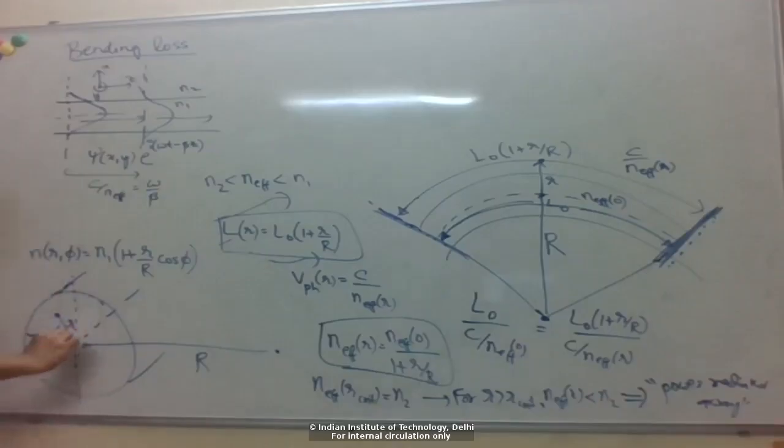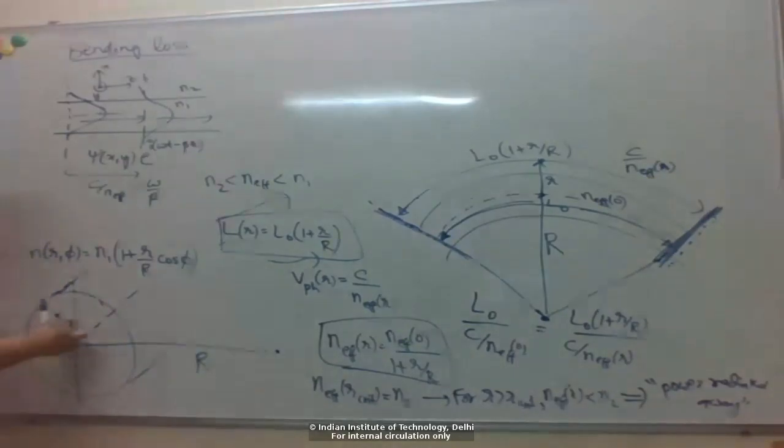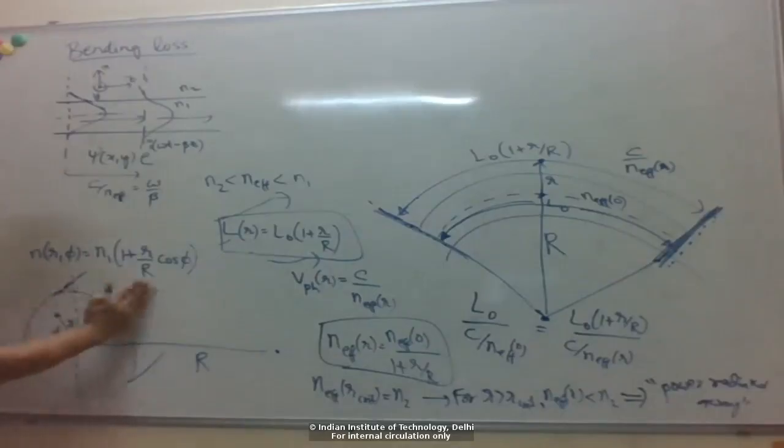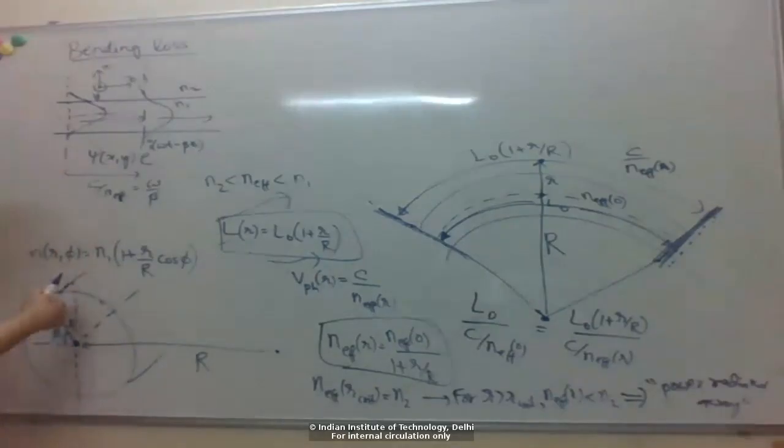And if you take, so imagine now phi equal to 90 degrees. That's a plane which is perpendicular to the radius of curvature here. Points along this are all traveling the same distance. On this plane, because it's bending into the board, all these points are traveling the same distance, unlike for this axis here, where all these points are traveling different distances.